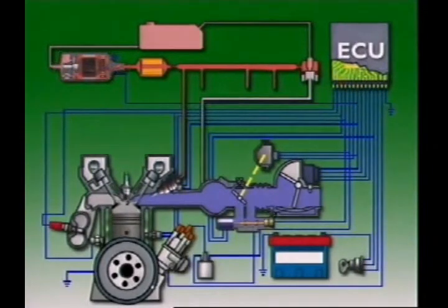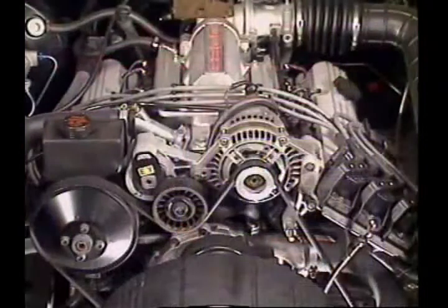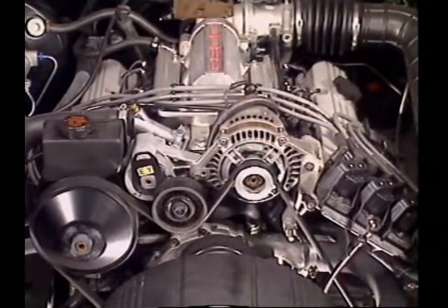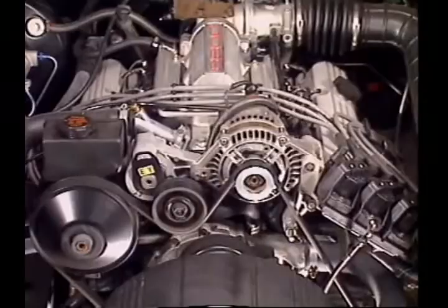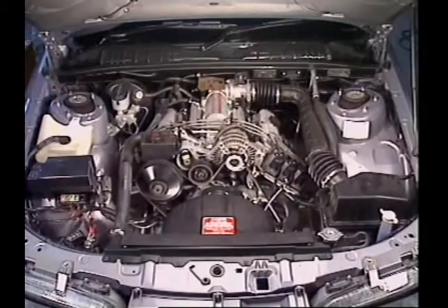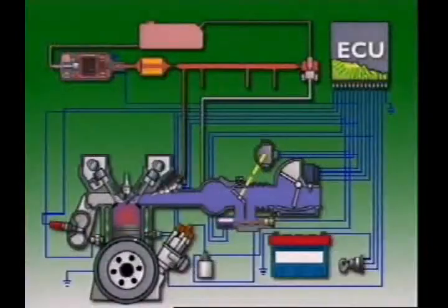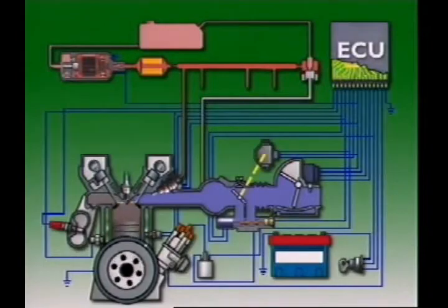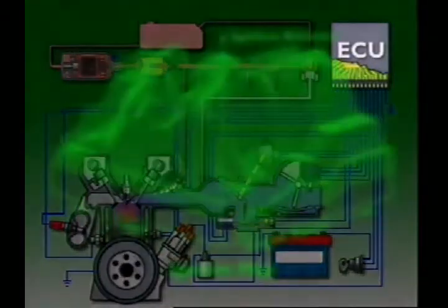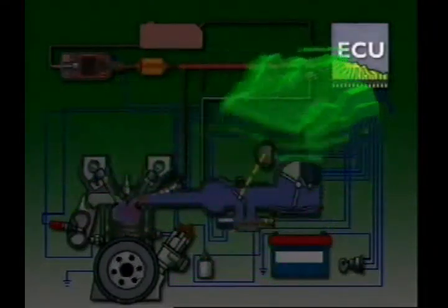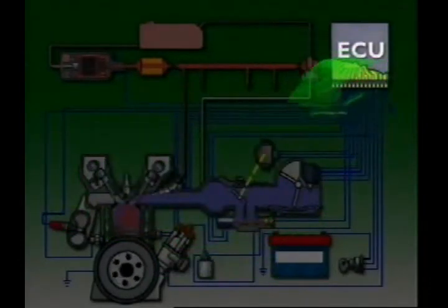These wider systems are called engine management systems. The more precise control they allow is very effective in reducing fuel consumption and exhaust emissions. The ECU adjusts quickly to changing conditions by using what are called programmed characteristic maps, stored in the memory unit. They are programmed into the ECU just as data is programmed into a computer.